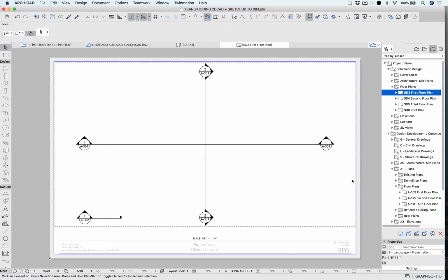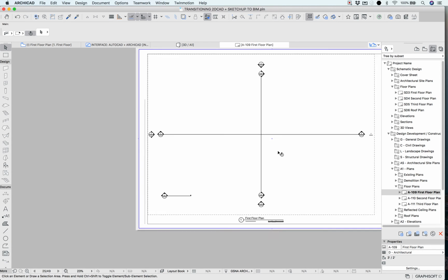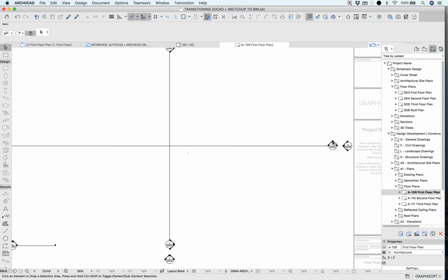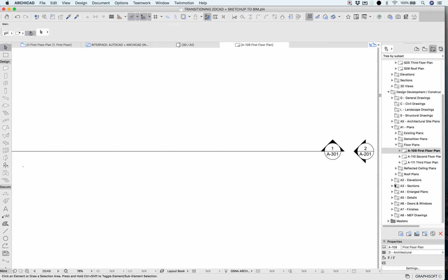And just a preview into what happens with our template is that the goal is that you're going to take most drawings that you use most of the time and include them, pre-placing them so that when you build them, they will populate. So for instance, our elevations are on drawing 1 on A301. Our sections and elevation markers are pre-placed, and what you'll find is that if there is a change, I will be able to make that change, right?